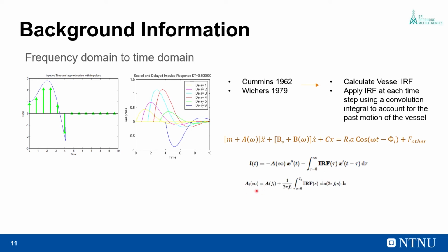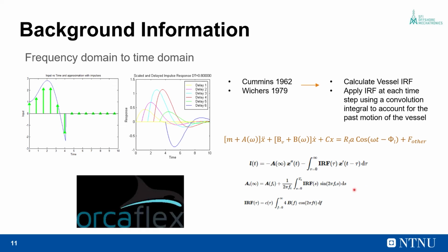response function. To calculate the infinite added mass, you need the added mass matrices at different frequencies. And to calculate the impulse response function, you need the radiation damping at different frequencies. And this is why you need to actually import the frequency domain hydrodynamic data into time domain software like OrcaFlex.